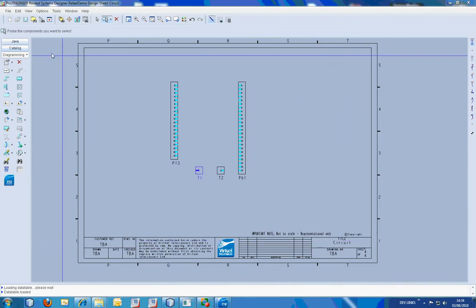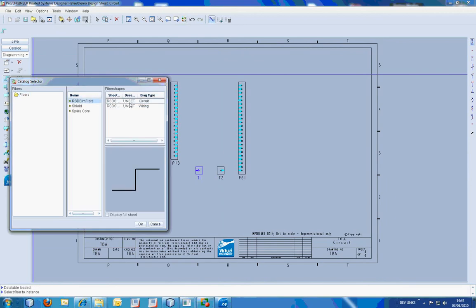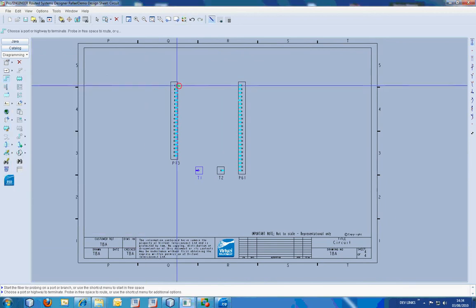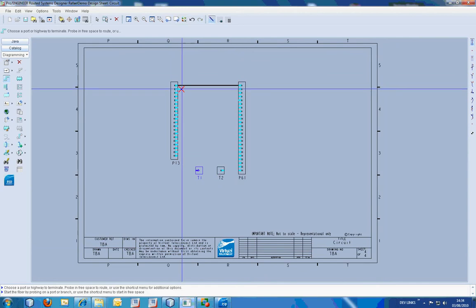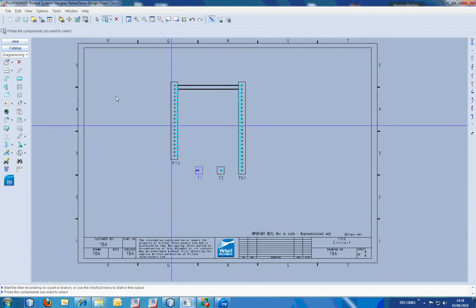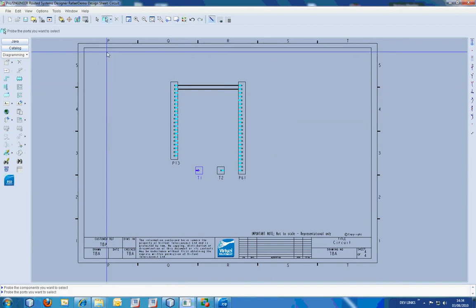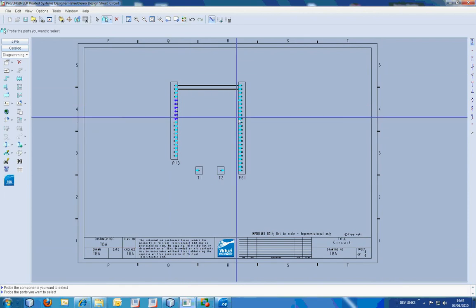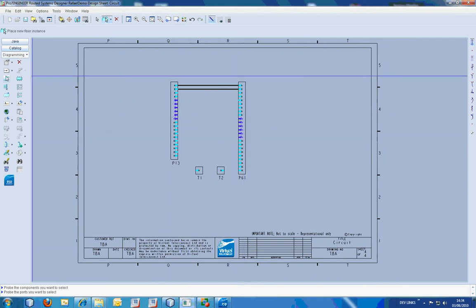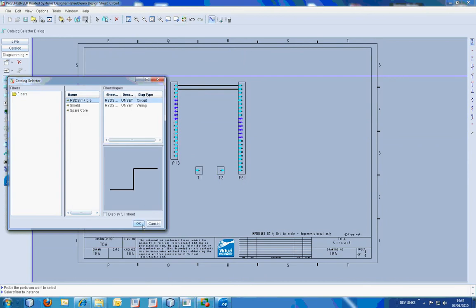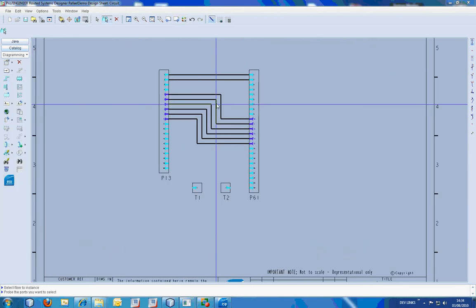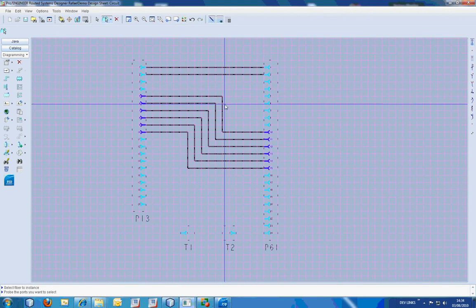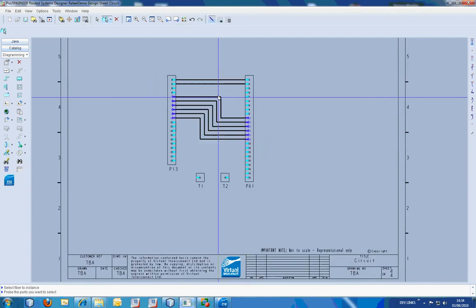The first one is routing fibers directly between pins, and the second method is where you can group select a number of pins from one connector or artifact and select a similar number of pins on a second connector or artifact, and allow RSD to automatically route fibers between these two. And as you can see here, RSD automatically offsets the fibers according to the grid pitch, which you can change.